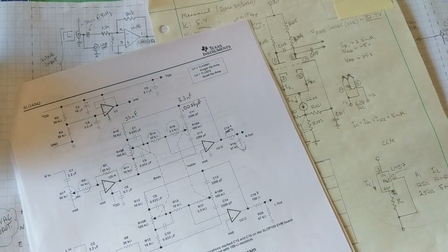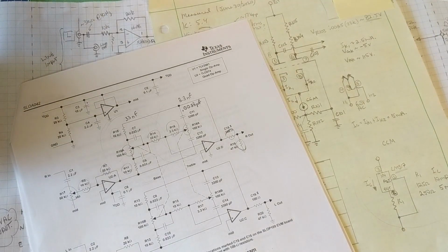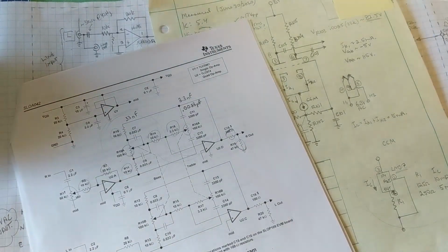I can also use that opportunity to do the final positioning for the choke and the low voltage power supply inside of the chassis, and also the power switch and the fuse, not the fuse, but the RCA jacks for the input and the pass-through. The volume control and bass boost cut is already designed, and I'll show that in the next video, what I did for that circuit. Both the low voltage power supply and the preamp and filter stages are going to be on PC boards. That just allows me to cram all of this into that smaller chassis. Trying to do this with point-to-point wiring would be really difficult, and I think the PC board seems to be